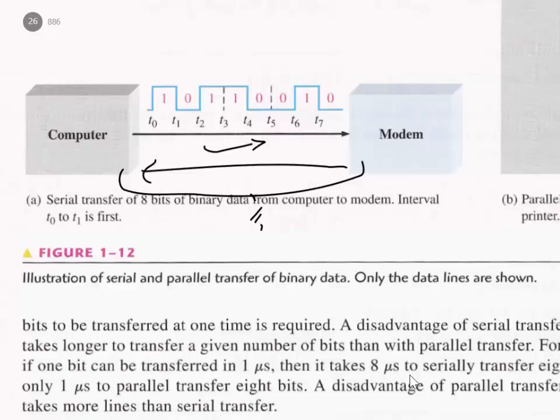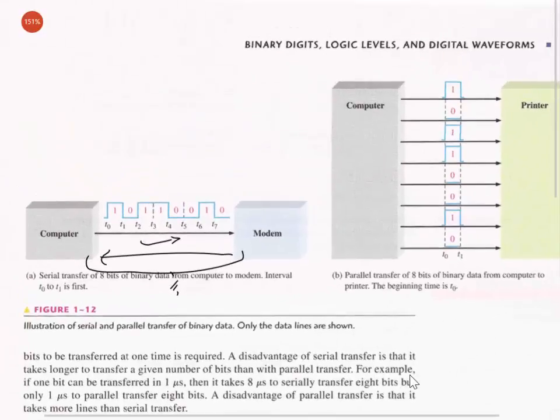If you use a standard 9-pin serial cable, pins 2, 3, and 9, I think, are the ones that are used. I know it's 2 and 3, and I can't remember which one. I think it's pin 9 on a 9-pin. Or we can use parallel.